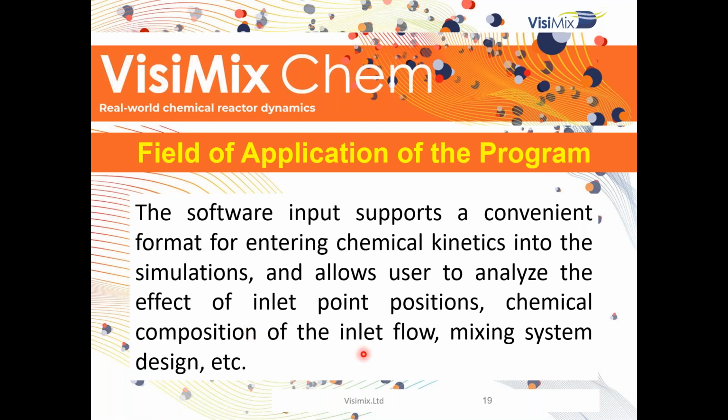This will need the chemical composition of the inlet flow. As you remember well, VisiMix is able to show what the different result will be if we feed close to the impeller or at the top of the tank. It is really important that we are able to do it. Now we are able to include more, defining the diffusivity well, not only by the non-uniformity in the tank, so we include another model that will be more precise.